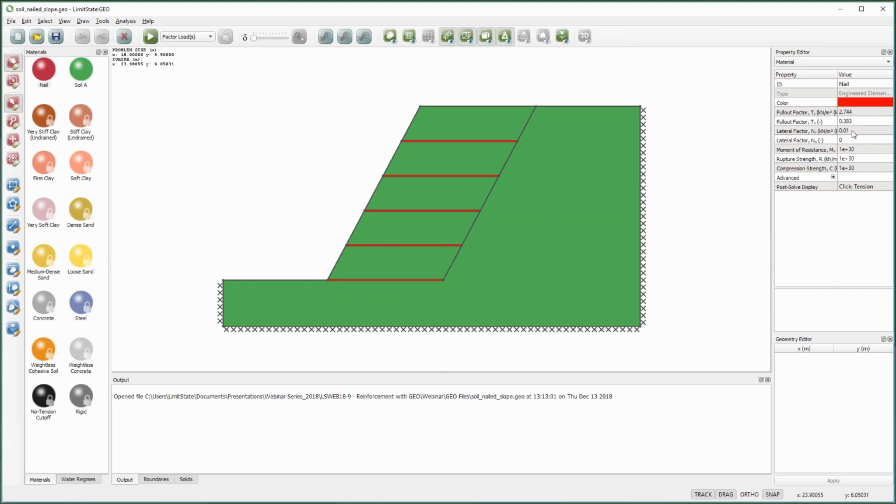If you do want to model that capacity, because it is there, you can increase those numbers. You would basically be looking to use formulae from pipelines or piles, which look at lateral movement of these things through soil, and then you can calculate the coefficients from that perspective, and it will give some additional resistance to the system, but one has to think about the ultimate limit state and displacements required to mobilize these kinds of resistances and so on before putting them into the analysis. Okay, so I hope that has answered that one.